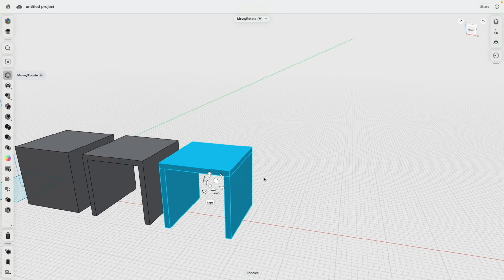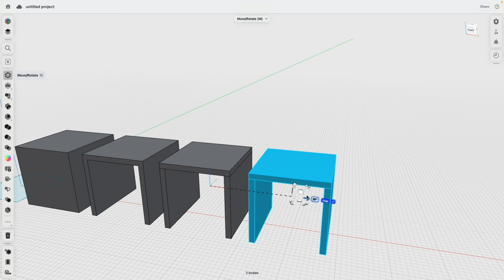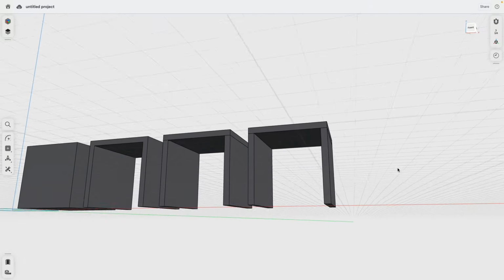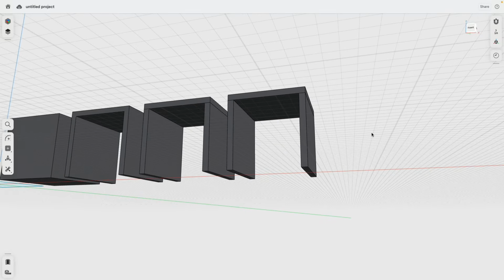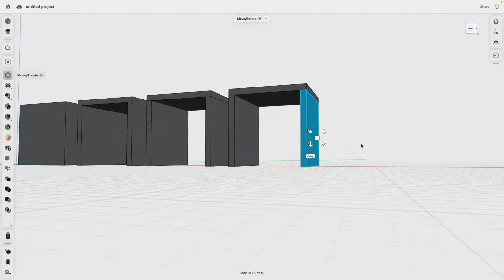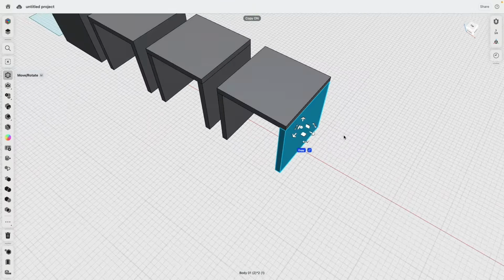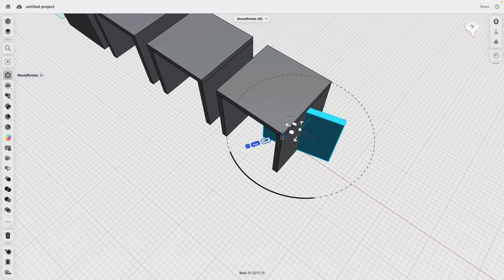So I will select everything, click, drag left to right, copy, and have another copy at 20 inches. I now would like to look into how I can make supports. Hence also this is super easy to do. Double click the left or the right side, doesn't matter which one. Click copy. Then we rotate this one 90 degrees.